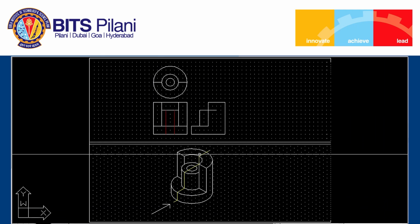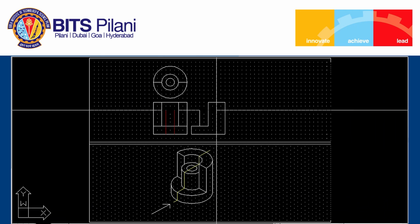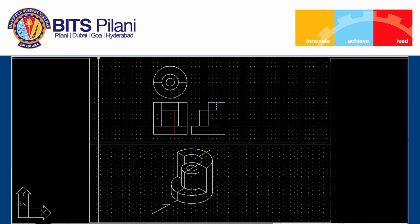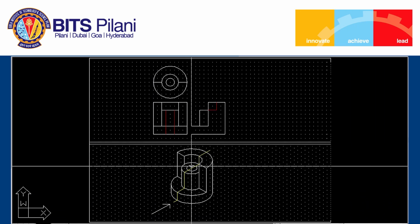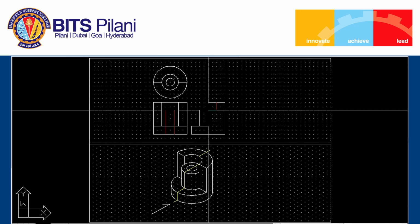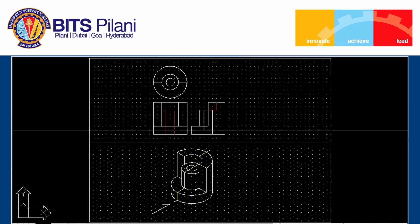But it cannot be like this. Then we have this curved surface, the inner curved surface. Okay, for this inner curved surface, this last visible boundary will fall into a line view, but it is not seen. So we will show it with the hidden line. From here we will draw it like this, and that is not visible, so it will be shown with the hidden line. Similarly, the hole we will have to show, which will be throughout the height, because its height is not specified. So these are the lines for the hole.